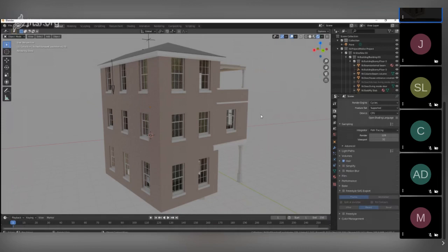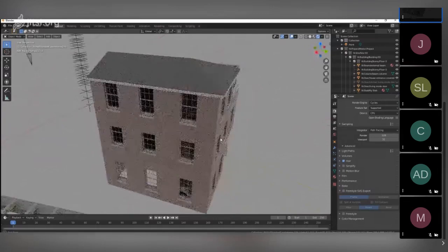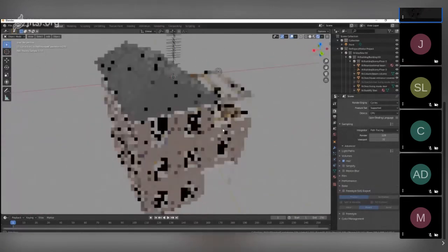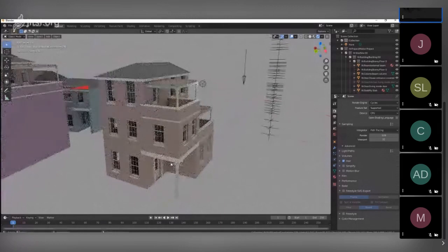So in the fitness calculation, I look at the floor area of the room and the amount of external wall, and it scores it appropriately. As you can see with this building, it has an awful lot of external wall for the rooms, but that's completely tunable. Another pattern is this 6-foot balcony pattern that we saw, and then there are various patterns about circulation, about how close living rooms and kitchens should be to front doors, and how far away bathrooms and bedrooms should be, and so on, and they're all implemented as well.